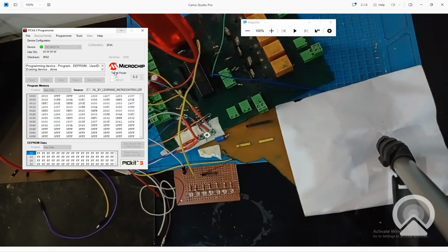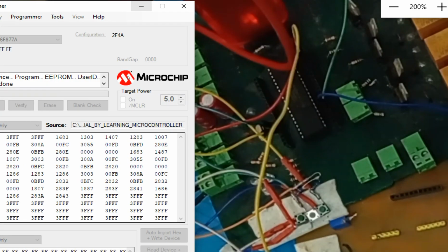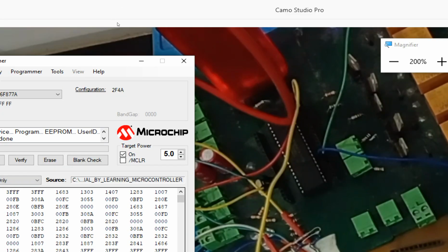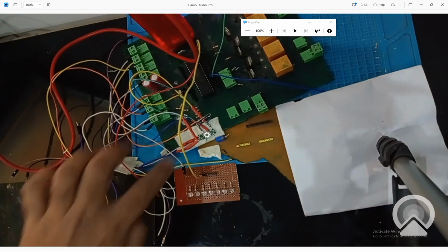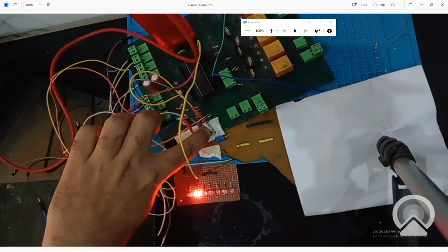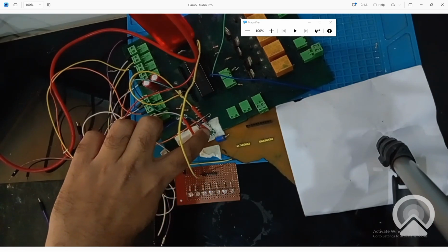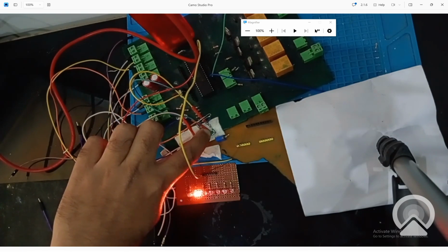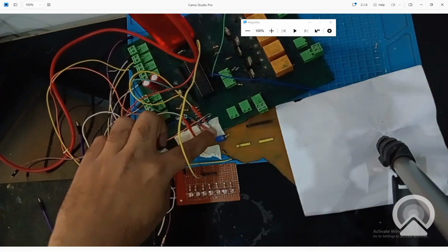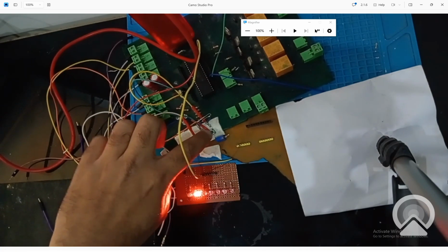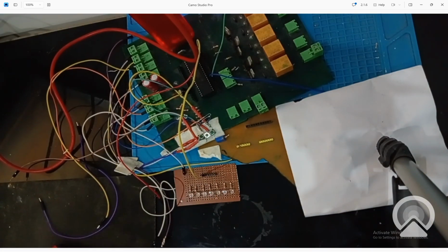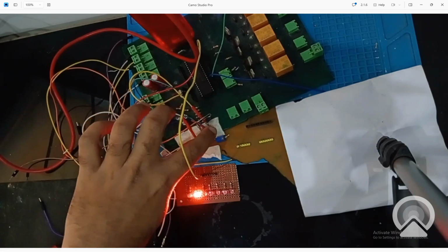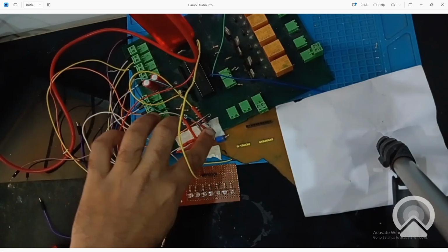Okay, the code is written and circuit should be powered up. I power it up using PIC16. So it's good that no LED is on by default because we are using else LED is off. Now I press the one button. See, the LED is on. That's great because it's an OR gate. If any one button is pressed, LED must be on. See, it's on. I press both the buttons, still the LED is on. That's great. Now guys, you can see that the truth table both have been verified.